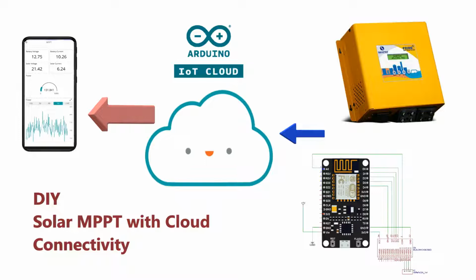So I thought of making use of an analog multiplexer, so we can have select inputs for choosing different channels. Since we have only one ADC, we can switch between the channels and read all 4 ADC values.